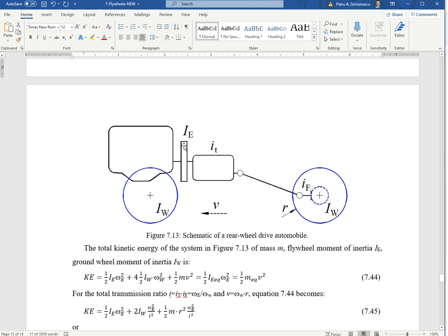It comes with some problems. You're going to transmit the fluctuation of torque from the crankshaft to the transmission at a higher level, so that fluctuation will be sensed at the higher level, and it can have a detrimental effect upon the endurance of everything downhill from the flywheel to the wheels.